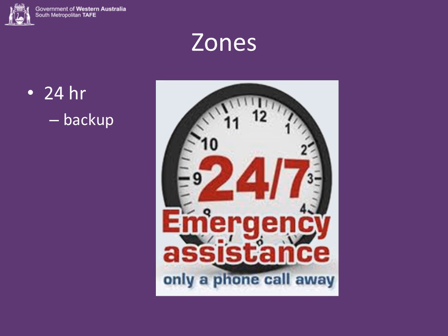Some places, you always have to bear in mind, need to work on a 24-hour schedule, and there needs to be some sort of way of doing this. Police stations, hospitals, they work on 24-hour schedules. Don't forget them. It makes sense to construct the air conditioning system such that the 24-hour zones come off a different air handler from the 9 to 5 zones.